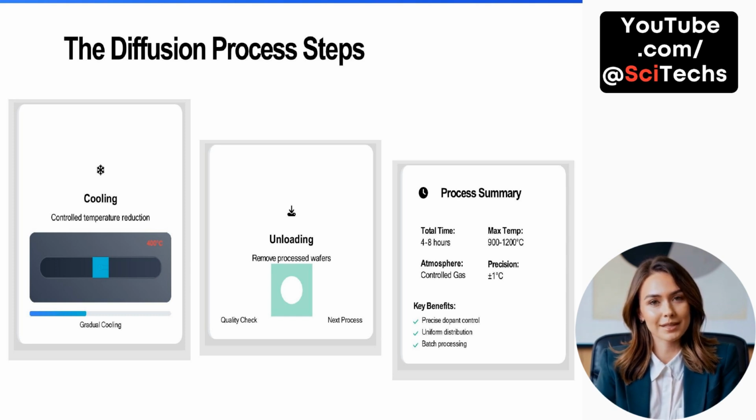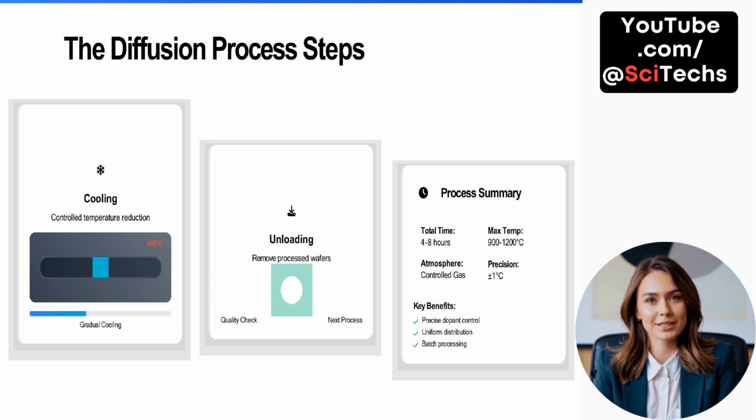In summary, the entire diffusion cycle spans 4 to 8 hours, reaching peak temperatures of 900 to 1200 degrees Celsius under a precisely regulated controlled gas environment. The process achieves plus or minus 1 degree Celsius precision and supports key benefits such as precise dopant control, uniform distribution, and efficient batch processing.